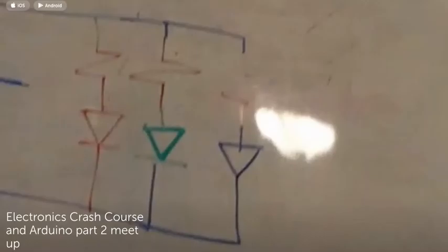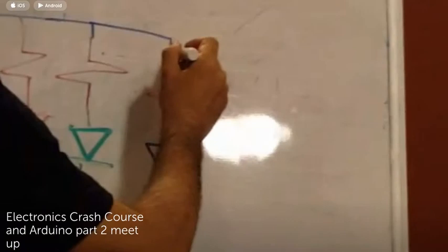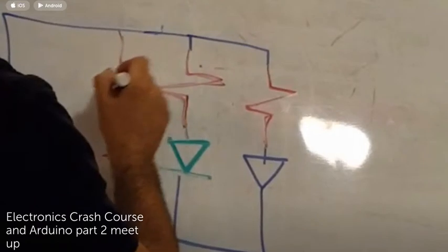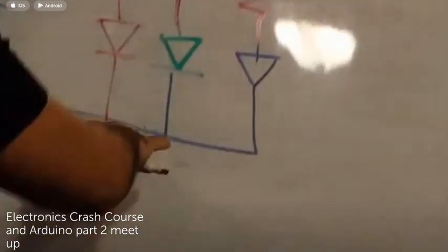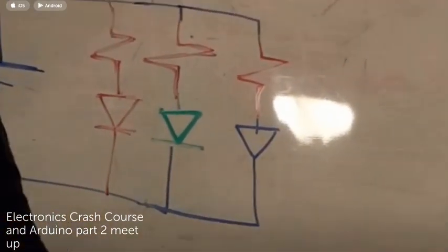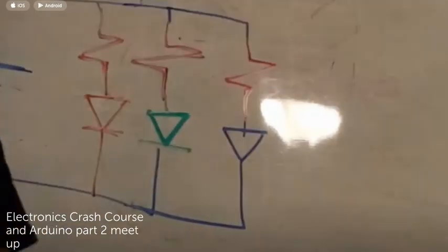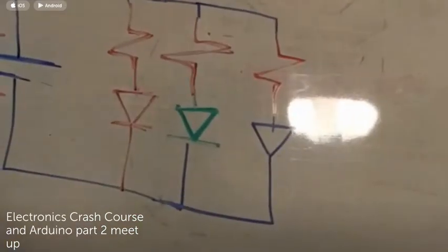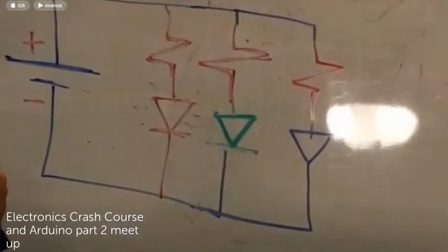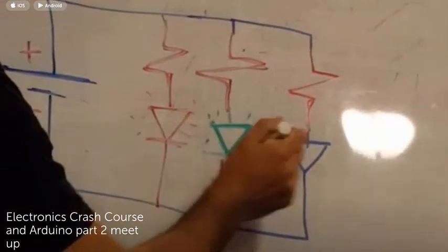This is basically the circuit that we're going to create. Three resistors, and each one of these is a leg of that RGB. And then one of the legs connects to negative, the extra leg of the RGB LED. And the power is going to be given by the microcontroller. So instead of using a battery and just these three, this LED will light up, but you wouldn't have much control over them. It would just be steady on, and that's it.